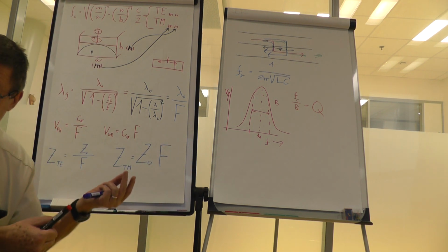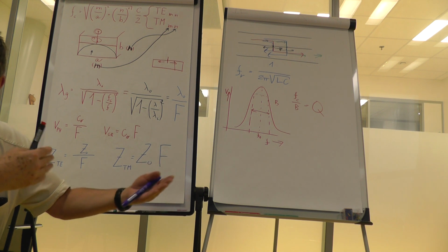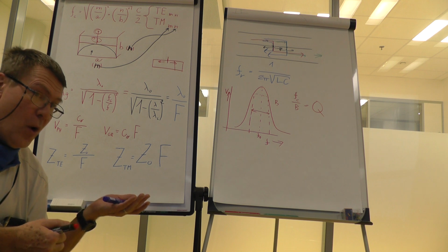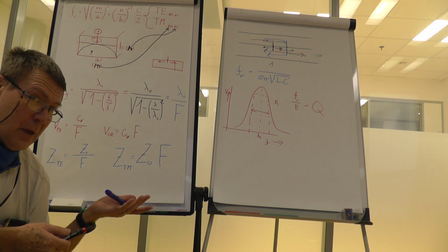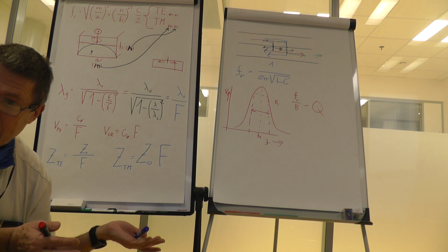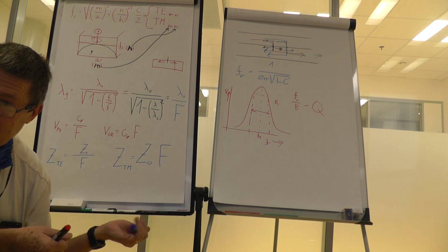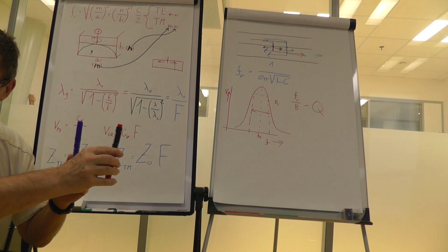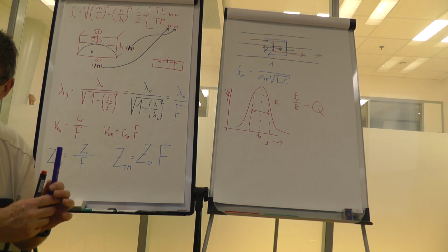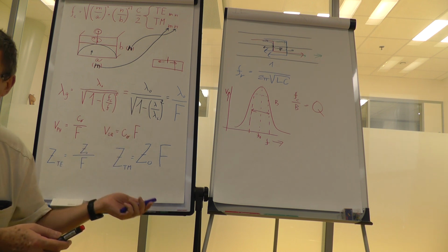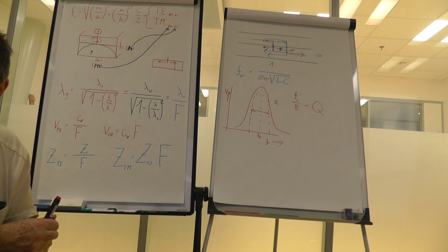And now, we mostly use resonance circuits or filters to filter out one part of the spectrum, for example, for amplitude modulation on medium waves, the spectrum is 9 kilohertz, the center, and 4.5 kilohertz on each side. And the more selective circuits you have, the more transmitters and stations could broadcast in the band.